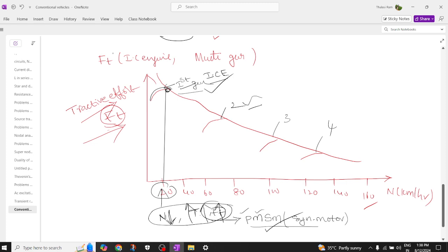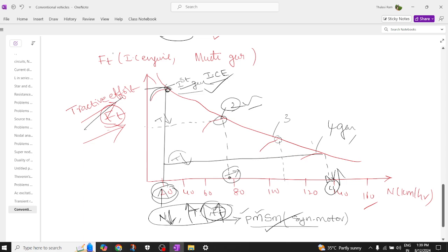In the first gear the speed is low, but at low speed it has more tractive force or tractive torque. Coming to the second gear, you can have better speed, so the speed is increasing, and automatically the tractive torque developed, I mean the pull, is much less. Why? Because you are already running in second gear. When you come to the third gear, the speed is increased and the tractive force is nominal. In the fourth gear you have the maximum speed, and the torque is moderate.